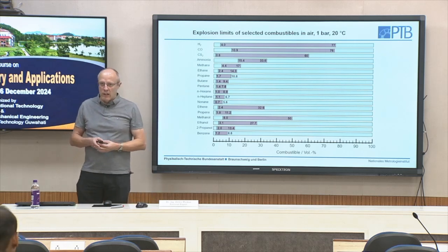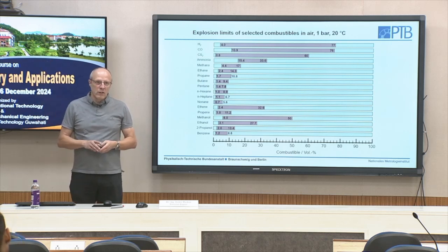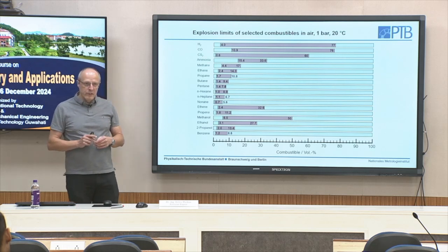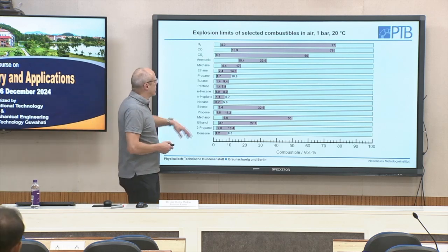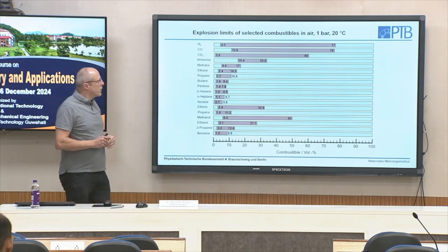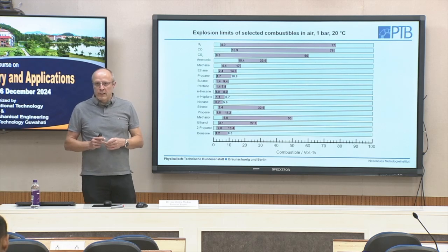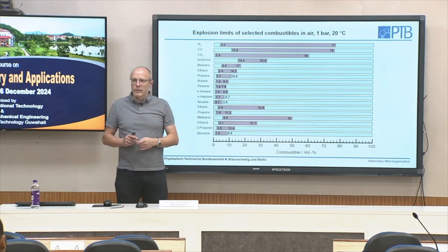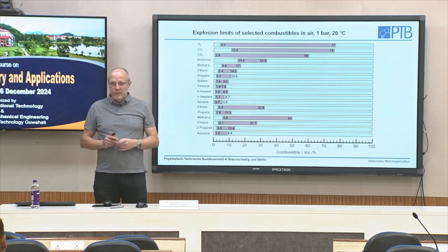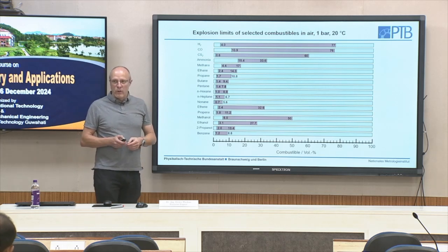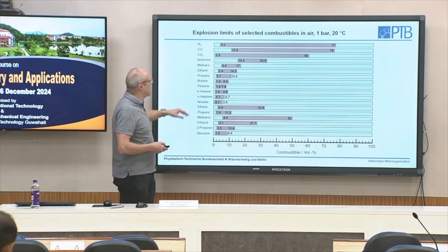As I said yesterday, in our labs we have gas sensors measuring the quantities of combustibles, and depending on the sensor, I think we are talking about a maximum of 10% of the lower flammability limit. So if there is a mixture with 0.4% hydrogen in air in our lab, the system already starts to warn us and eventually shuts down all electrical power supply.